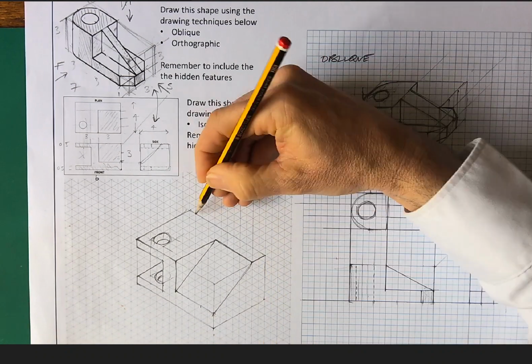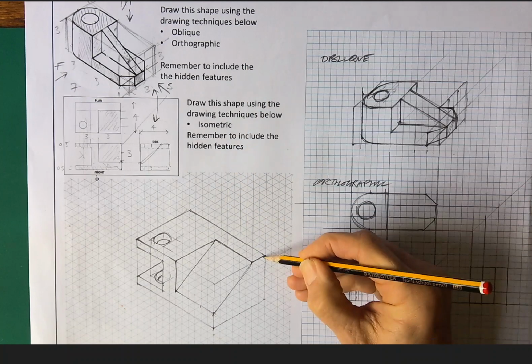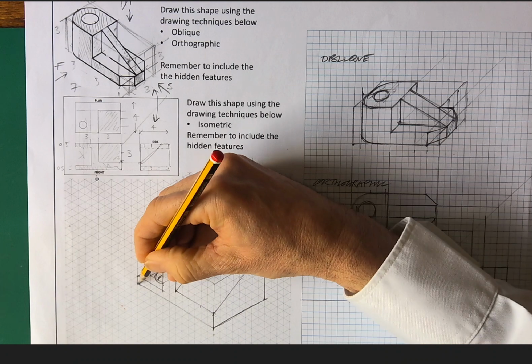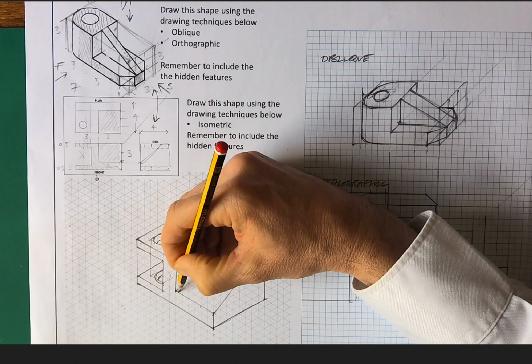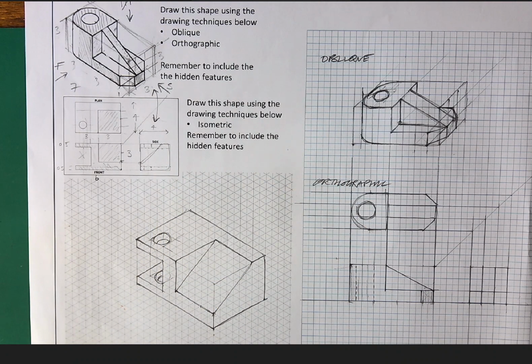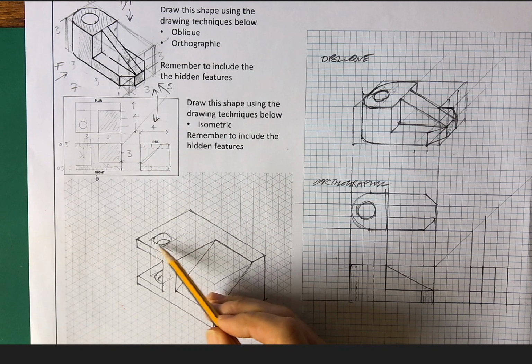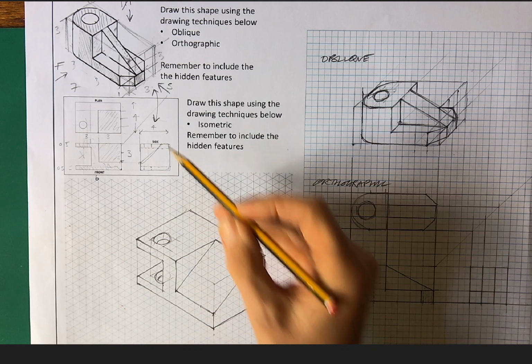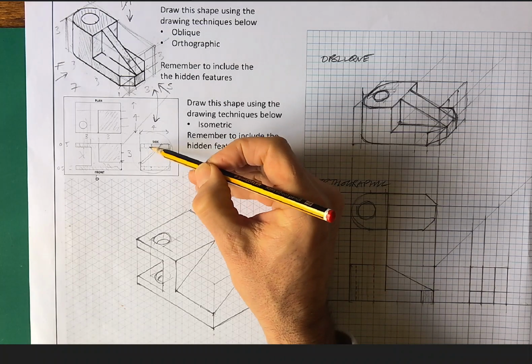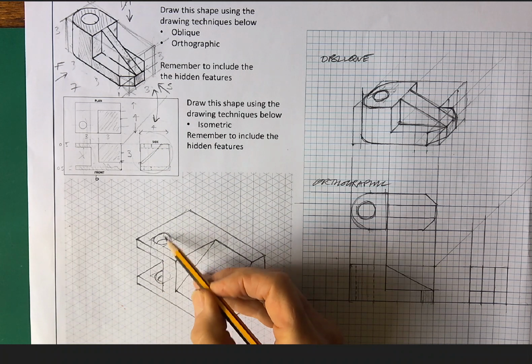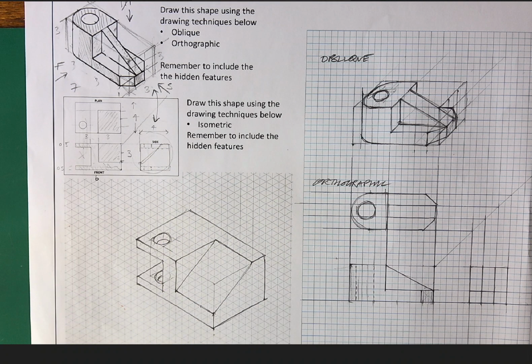Which, to be honest with you, once you break it down into form, once you rationalize it and you get some proportions, it's not that hard to do. Just look out for those dotted lines that can be confusing. They are to symbolize obscured areas which can't be seen. Okay, so for example, we couldn't see this negative cylinder because this was in the way on the side projection, and yet they were still within the drawing, and that allowed me to know that, okay, I have got a negative cylinder on the top overhang and the bottom. Right, I hope that helps, and it is of some use.